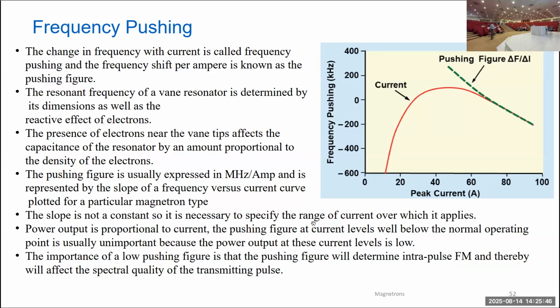The importance of a low pushing figure is that the pushing figure will determine intra-pulse frequency modulation and thereby will affect the spectral quality of the transmission.